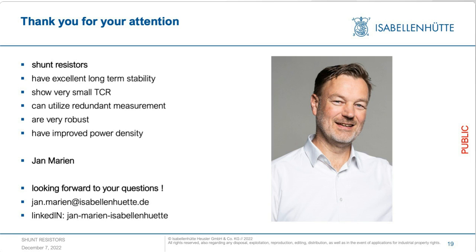Are shunts applicable in designs intended for functional safety? Thank you for that question. Yes, shunts are available for designs which are intended for functional safety. I have to mention that the shunt itself, as it is a passive component, cannot hold any ASIL rating.